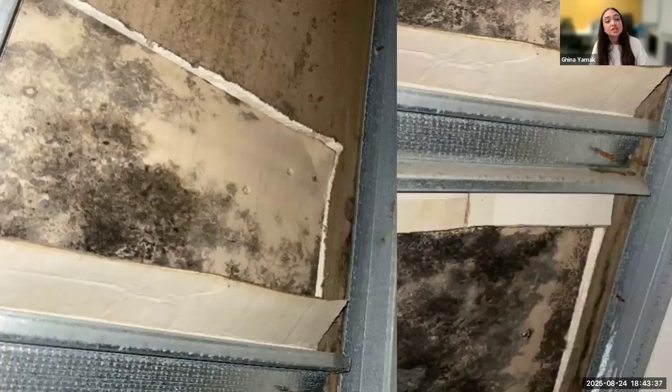Those are just examples as well from the interior, how fungus can go into the furniture. This is really a very hot topic in this market, because for example, during the summer in this country, the humidity and the heat is really high and people tend to leave on vacation and so on, and we tend to close our places without AC and leave. So what happens there is the game of the dew point, and the nasty game of the dew point, where the surfaces start to accumulate humidity, and the humidity will start being accumulated behind the levels. You wouldn't see it, but it's just there. So it's a very risky item, and all that is because of a badly installed facade or a badly designed facade. Who knows, whoever, during the process, something misalignment happened, and the result is this.